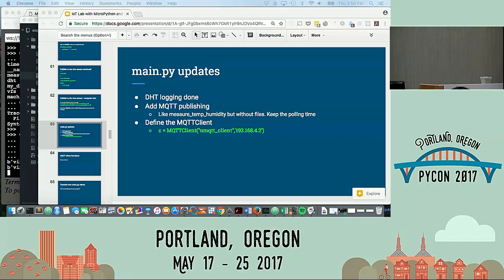So what I would do is, I'm trying to remember if I had the port number on there, but try changing that over to your 192.168.42. Okay, and close and open down here. Yes. Okay, great. So that is connected. And then if you come down to new under subscriptions and put the topic name. Something like this. Or you could just do the sensor topic and /pound, and it would give you all of it. So then if you send to this topic from your board, it will receive it and show it to you here.